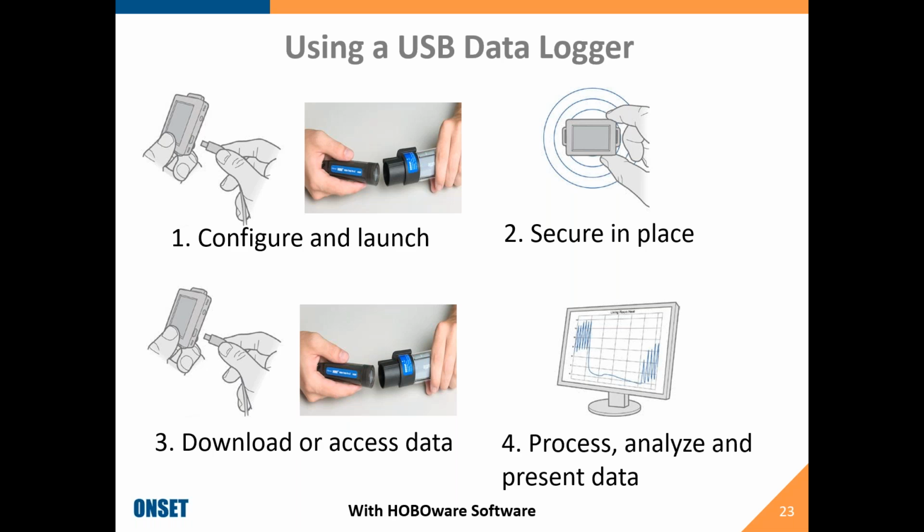You're going to place them where you need them to be. And I briefly mentioned floor to ceiling, or in front of an air conditioning or heating vent, would have an effect on how they're reading. And you're going to leave them in place and you don't have to be there. When you're ready to see that data, you are going to reconnect it to your computer and open up that file. And it's going to ask you, do you want to save it? Do you want to read it out?